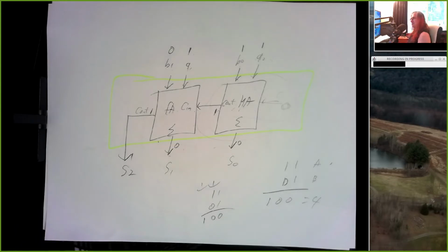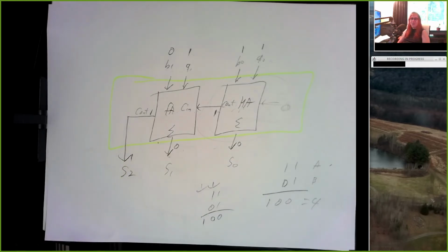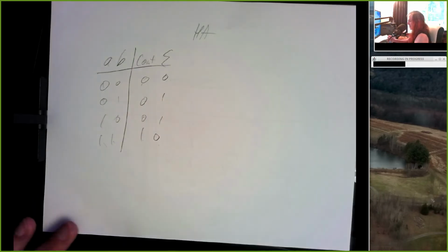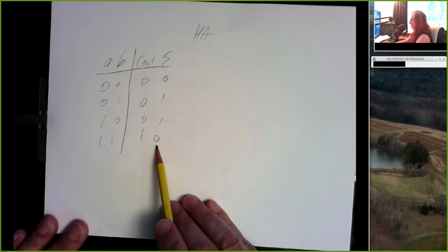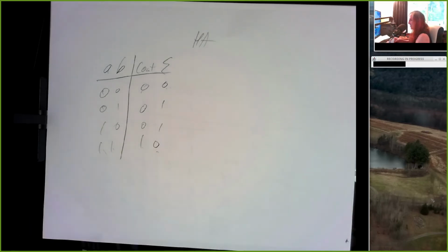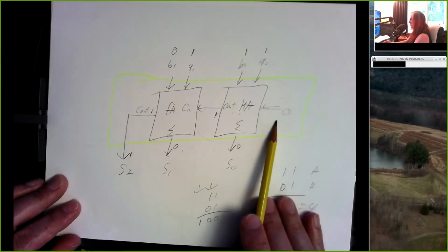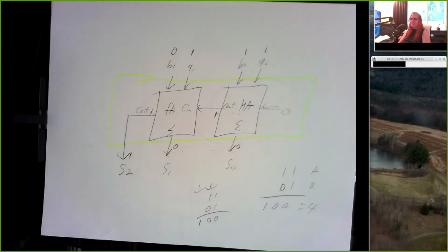But it ends up being a lot more circuitry because this full adder has 3 inputs and the half adder has only 2 inputs. And this is really just an AND gate, and this is really just an XOR gate. So you can get a half adder with a pair of gates. And it's like 1/4 of each of those gates. But yeah, if you wanted to, for some reason, actually use a full adder here, just connect that carry into ground, works perfectly well. And you still get full credit for that.